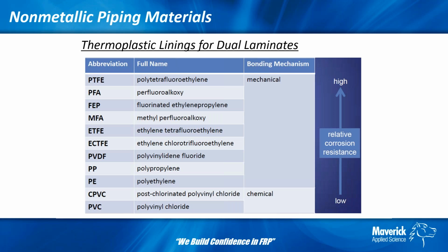I don't know that it's a lot different. I can't say that I've measured it, but my experience would tell me that if you're at a surface of, say, 90 degrees C on the inside, that FRP structural component is probably going to see something in the order of 70 degrees C. There's going to be a temperature drop across the thermoplastic because it does have insulative properties, but it's not going to be substantially different.